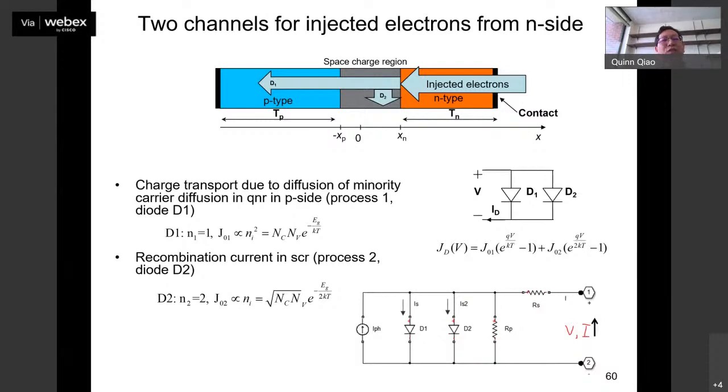Yeah, so that's what I say. Maybe photo-induced defects. Most probably under the illumination, because you have some defect, some problem in the devices, you have accumulation of the charge inside the devices. And that changes the electric field distribution inside the devices. That's why you see the curve look like two diodes. You generate a lot of photo charge there, the photo charge is accumulated inside the devices, and you generate a local electric field. That causes the issues there. Is this due to an interface problem, or is it a bulk defect affecting more in this situation? Oh, that's a possibility.